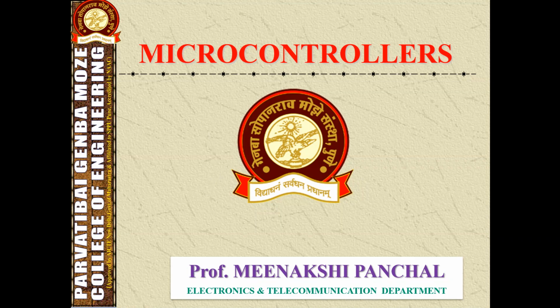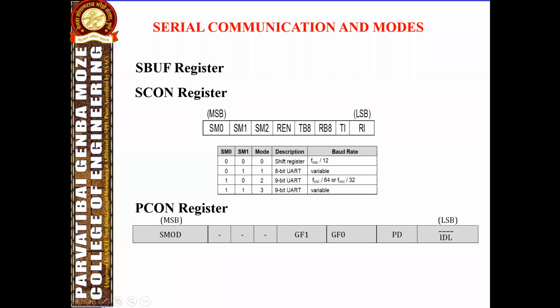So today in this lecture we are going to study serial port communication of the 8051 microcontroller. So let's begin. For communication between two computer systems, we can send and receive the data bits serially. The 8051 microcontroller supports full duplex serial communication. A full duplex asynchronous serial interface can be implemented using the serial interface control circuitry.